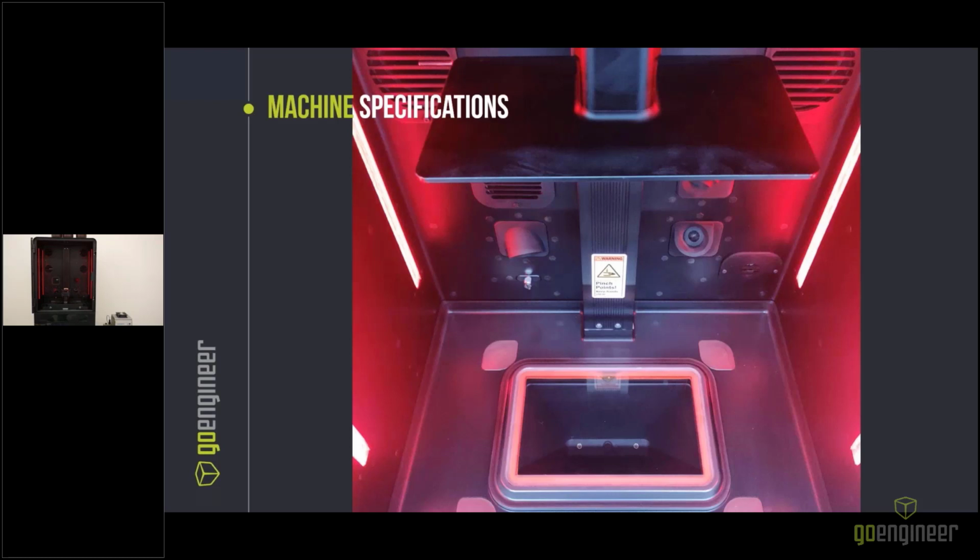We're going to start up at the top, looking at the build head, where we have some load sensors that measure the printing force being applied to the part throughout every moment in the printing process. This enables real-time feedback and closed-loop control, verifying that your parts are not being put under too high of a force environment.